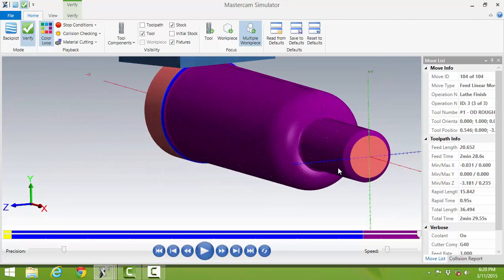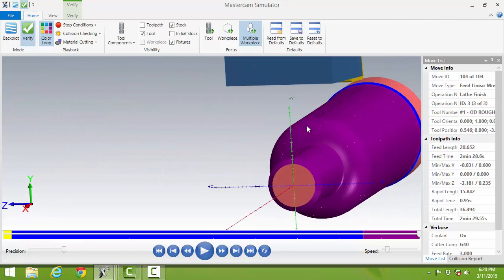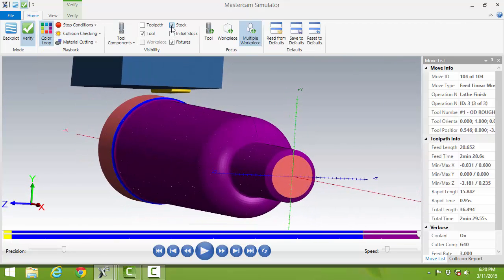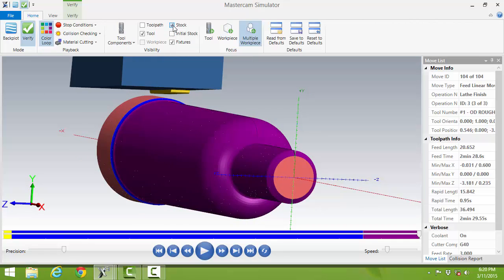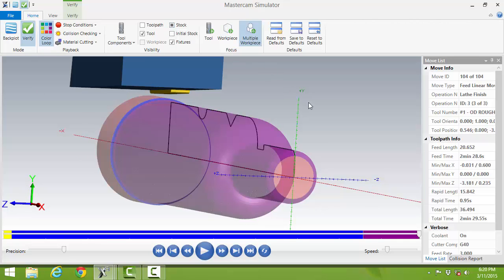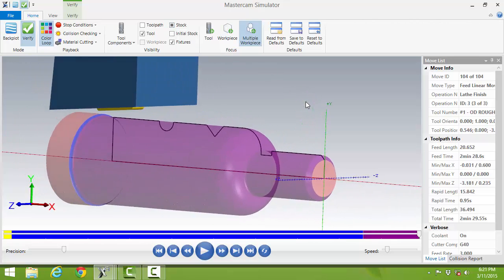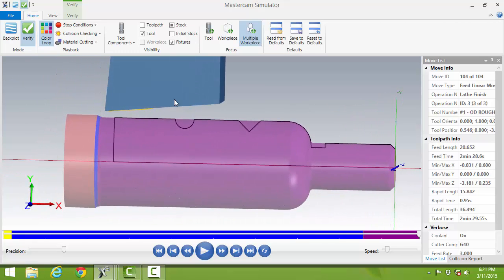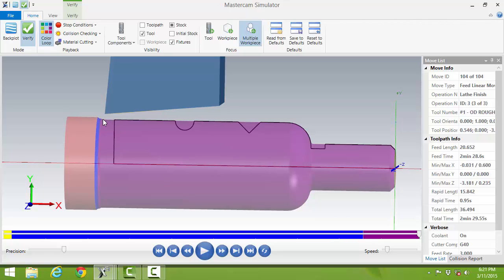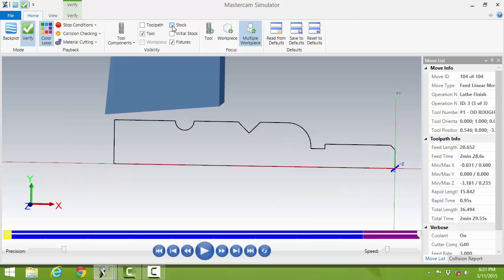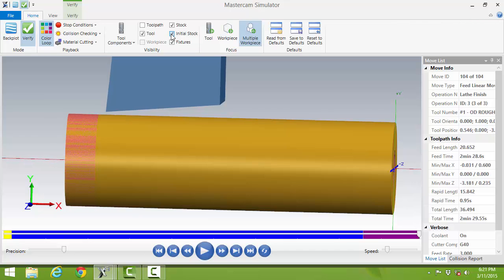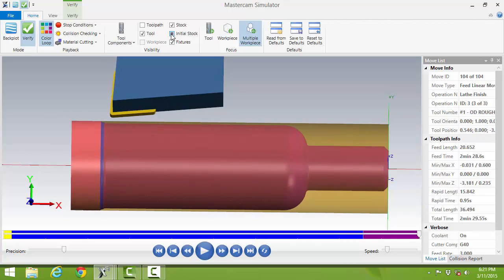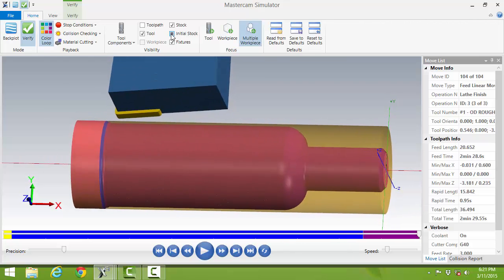We can rotate it around. It's 360 degrees around. It's following the tool path. You can see it. One of the neat things I just showed you is to turn the color on. We can also touch this button right up here, stock once, and it makes it translucent. So we can see our part and calibrate and see if we're right on the money. And it looks like we're doing very well with tolerances. You can see the clear out, the extension here. Very neat. If I turn it again, it'll turn it off, turn it on, show the initial stock that we started with. Make it translucent. There's our part machined. That's how much material we removed out of it.